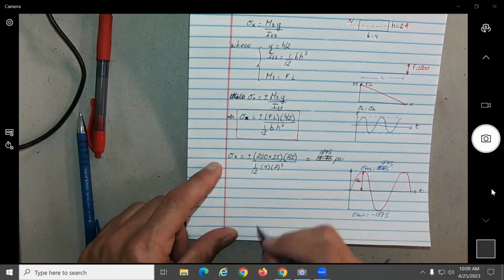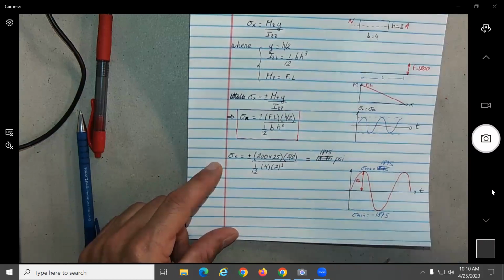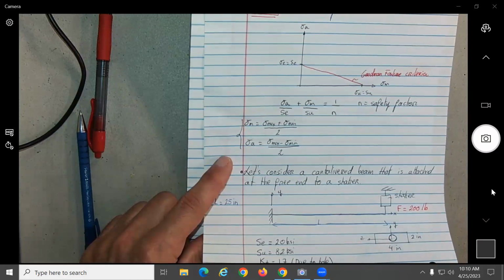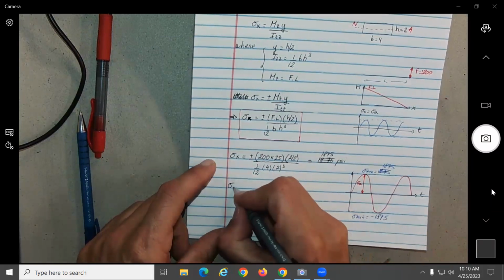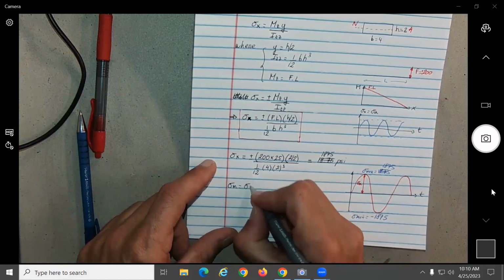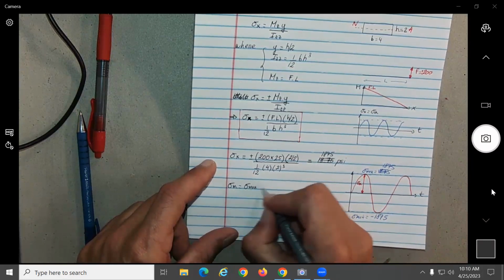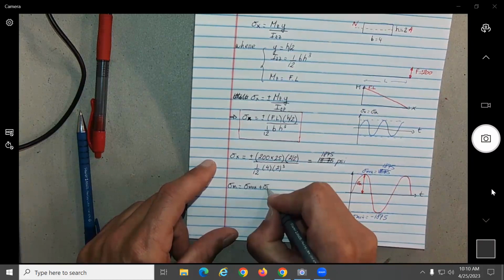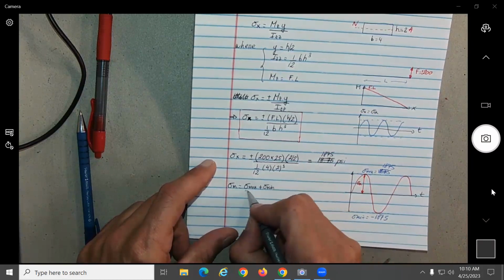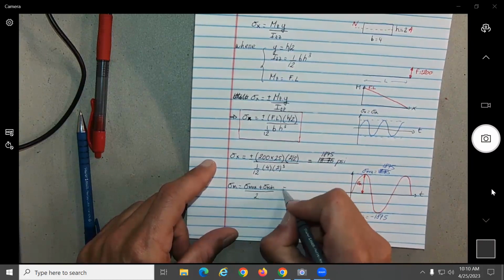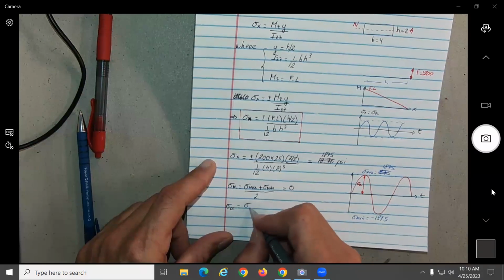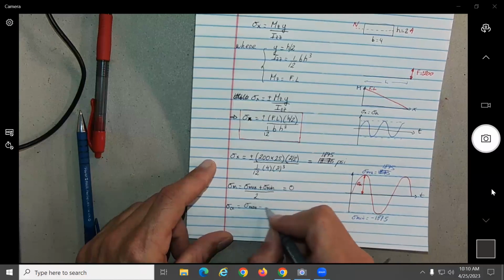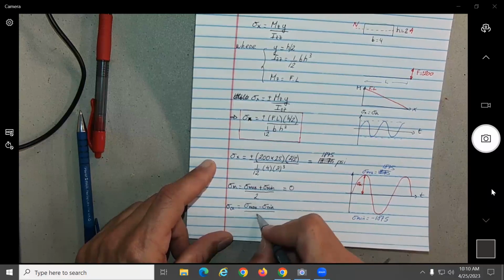All right, so from the equations I gave before, what will be the medium or the average stress? From the figure, it should be zero, no? If you do the calculation, it should give you zero. The alternating is going to give you what? 1875. I did it very simple here because you don't want to complicate it.